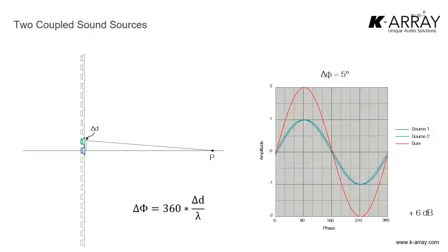Of course, we have two sound waves that arrive on the microphone location, and these two sound waves are a little phase shifted, because the green woofer is farther from the microphone than the blue woofer. So the two sound waves are not perfectly in phase, they are a little shifted. But if the two woofers are really close to each other, we can assume that the difference in the two paths is much smaller than the wavelength we are considering.